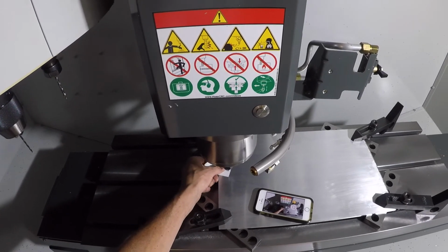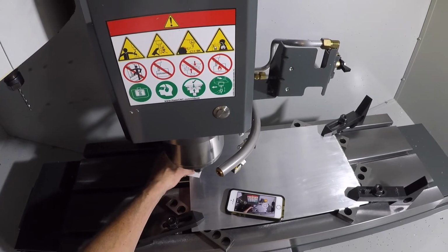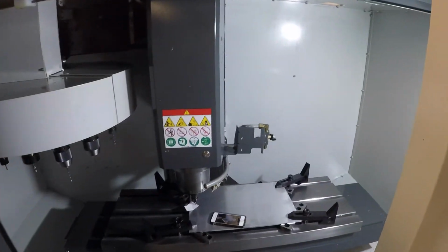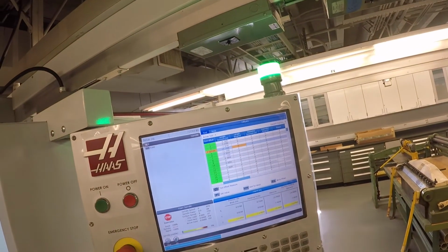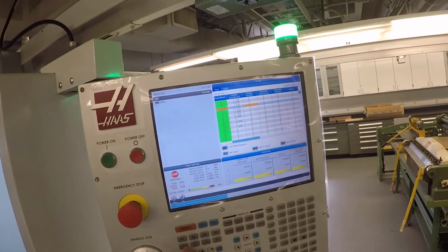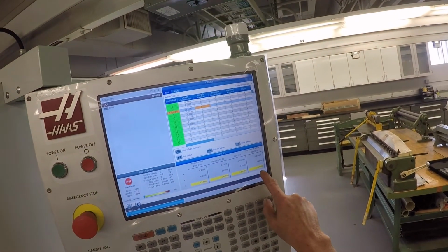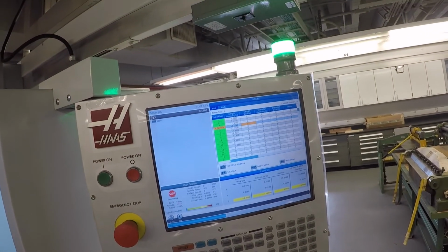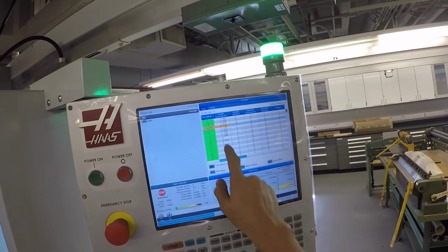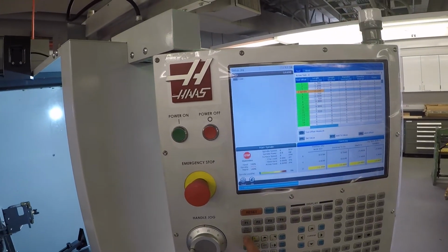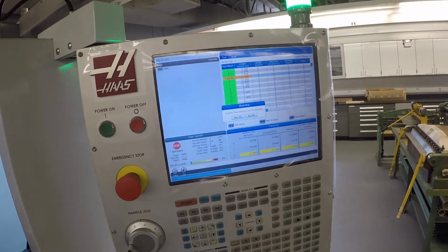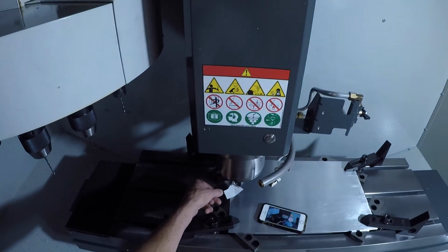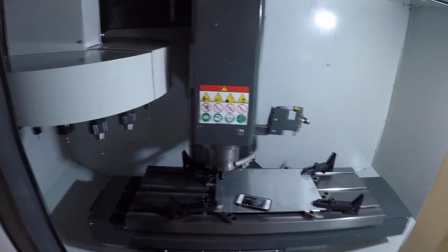Right there, see it? So about 3/1000ths off the top of that. So 1, 2, that's fine. I'll just do that. And it says right here, tool offset measure. We can see we're highlighted in Z, and we're going to see 13.46 pop up to that. Make sure it's highlighted, and pop up to that. So tool offset measure. And then move this off, positive.